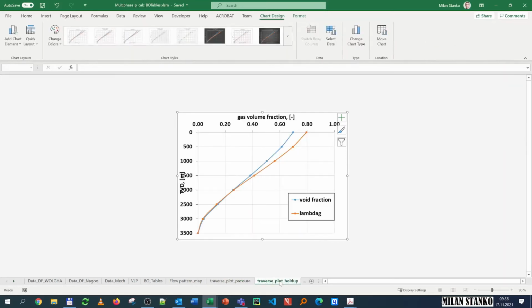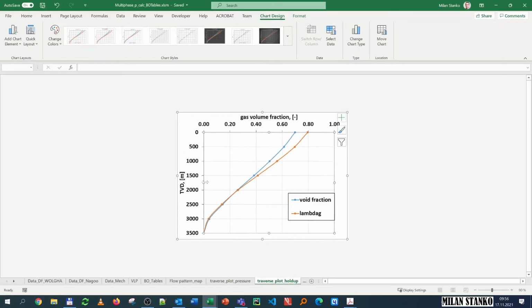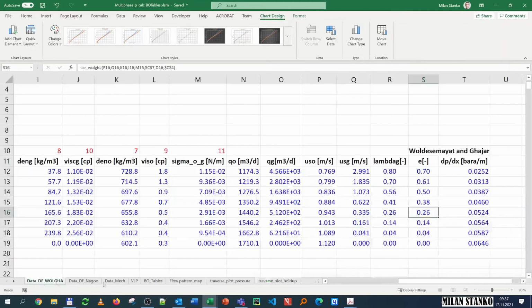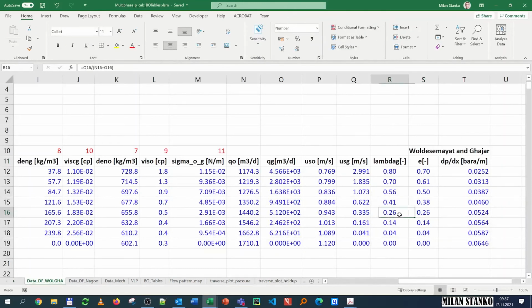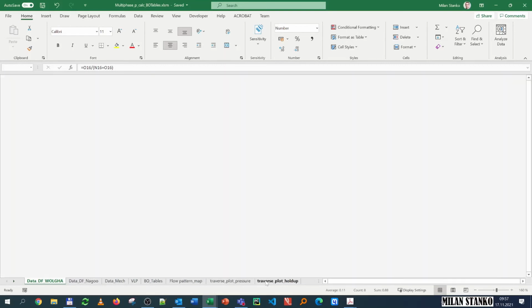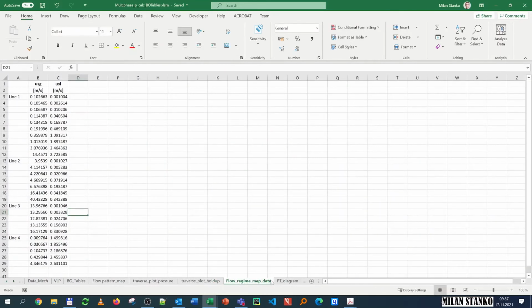And then this is the gas volume fraction. If I use the slip or the non-slip, you see initially here there is a big deviation, but then when I go and I have less and less gas, actually the gas travels at the same velocity as the liquid. And we could say maybe that here these two are different up here, but then here they become very similar. There is almost no slip according to this correlation. Let's see what else do we have?